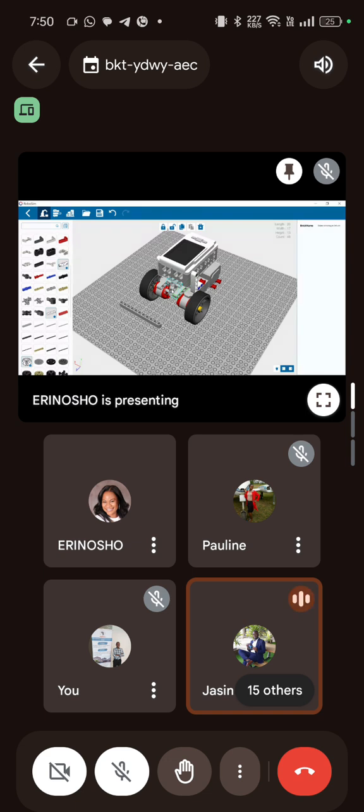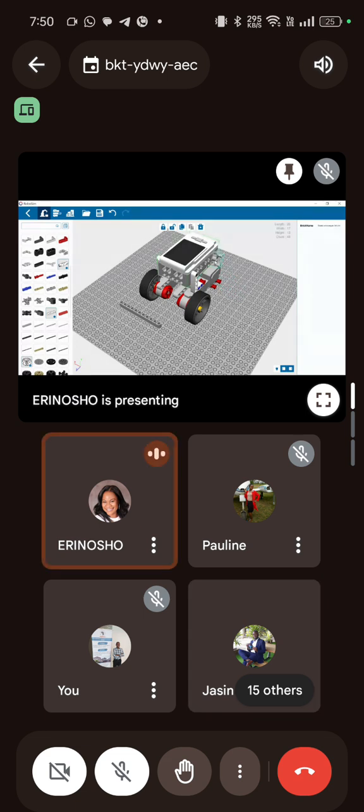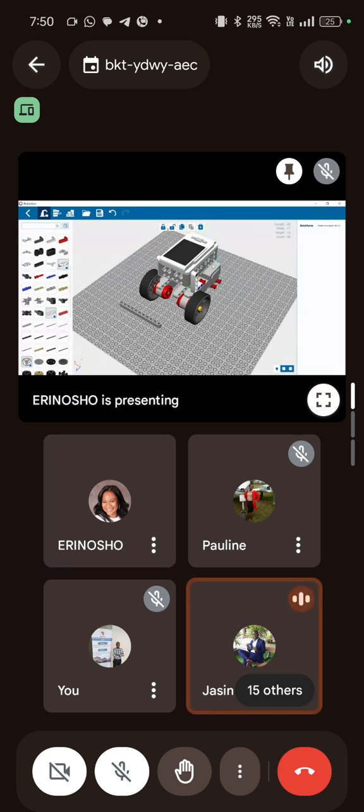Now, can you see where the buttons are on the side? The powering button on the robot, and just continue moving it upwards. Up a little bit. There are 3 holes, the last 3 holes. Did it lock there? No, it did not. I can see it's not at 90, so you'll be having a challenge. It's not at 90, so make it 90 first.